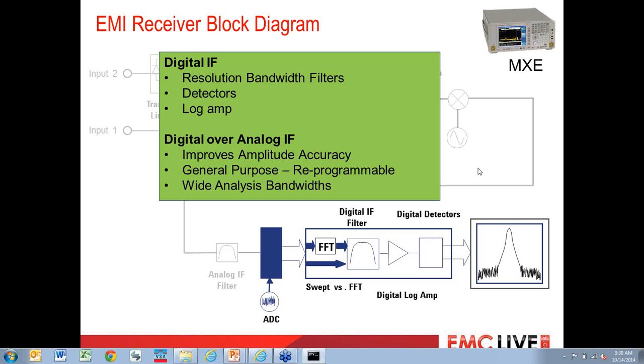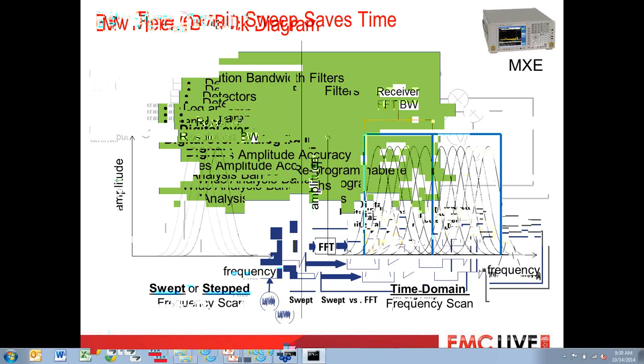Then, lastly, what was introduced in 2010 is called time domain scan, and it's essentially a very fast, highly overlapped FFT. And it's allowed for pre-compliance measurements as well as full compliance measurements. Now, to illustrate the time savings here, I have a slide.